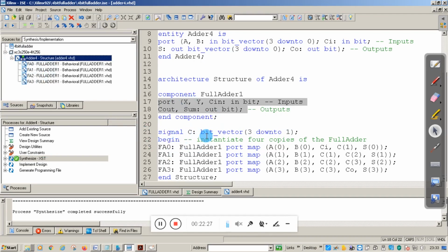Once this is done, we will proceed to the test bench, and we can see the output in the test bench. Related to test bench, I have already told you how to give the input. In the same way, you have to give the input and check the value for either 2 combinations or 3 combinations. In this way, you can implement this 4-bit full adder by using full adder. This is called the structural way of modeling.